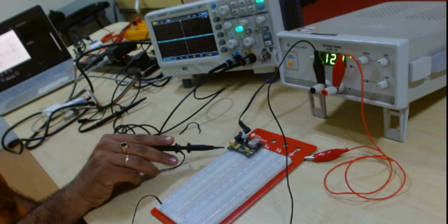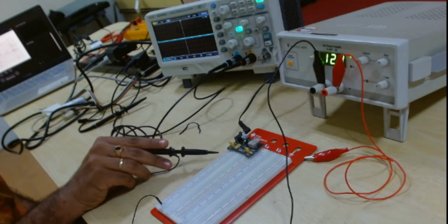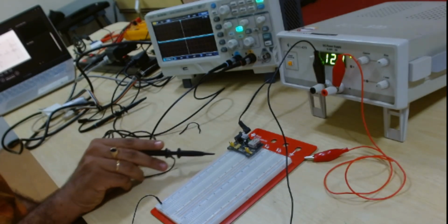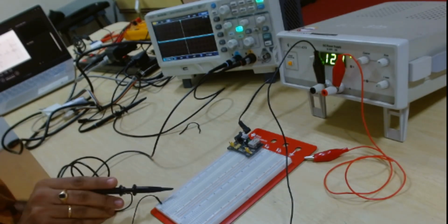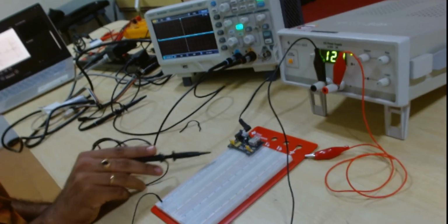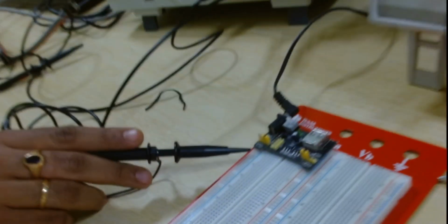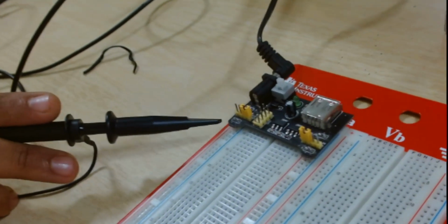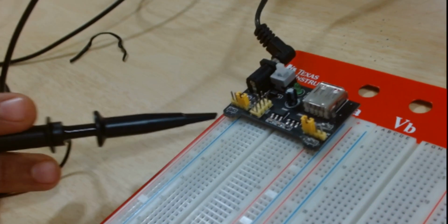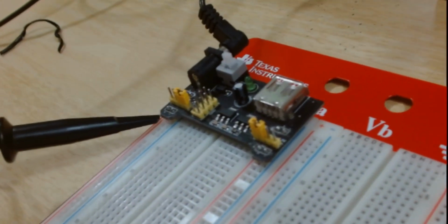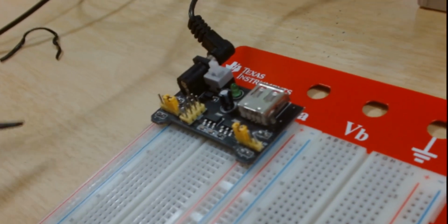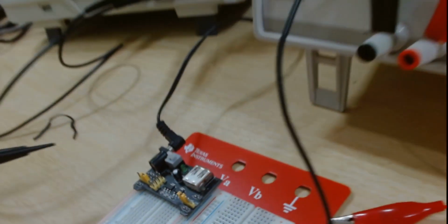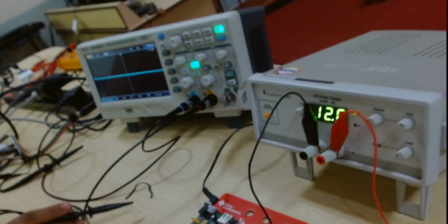See these two pins here, which I am connecting to the extreme connectors, or the common supply track. There I have both the positive and the negative. This side is positive, plus 5, and this is ground. So these are where I get the plus 5 volts.